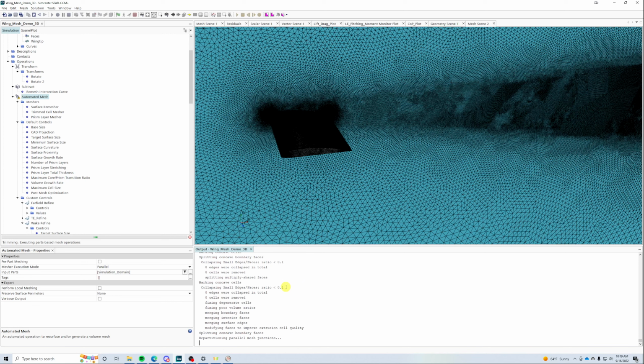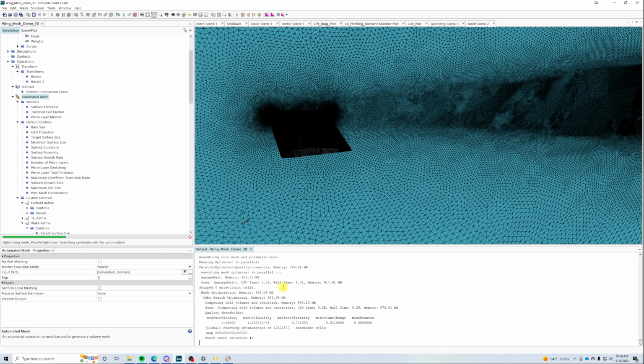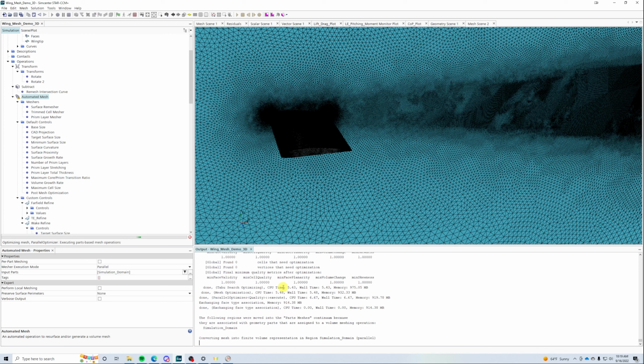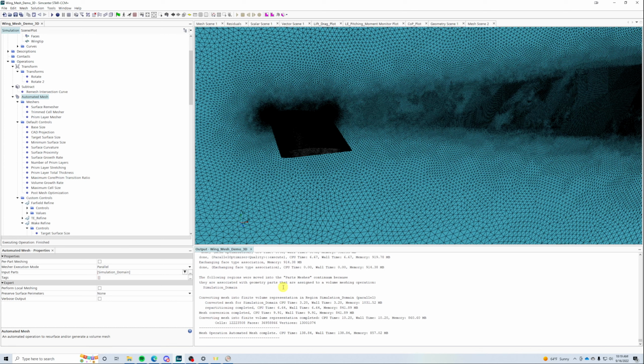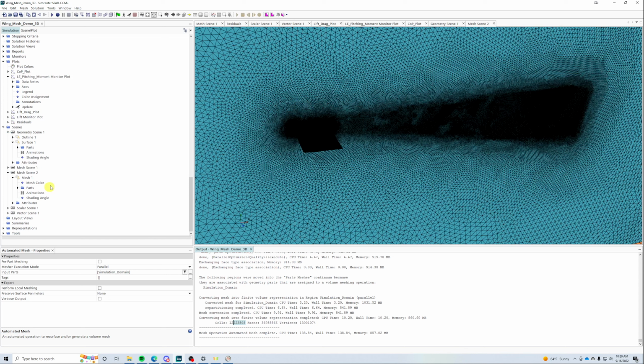Mesh quality. Because this is three-dimensional, it will have many more cells. But it's also parallelized, which means that it's making many more cells, but it's actually using more than one core. In my case, it's using 14 cores. So, while it has more cells, it's also running faster. In this case, we have, let's do a little bit of vision here, a little bit overkill maybe, 12 million cells. This is quite probably a bit much, honestly.